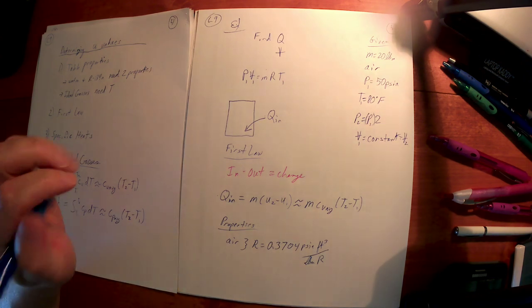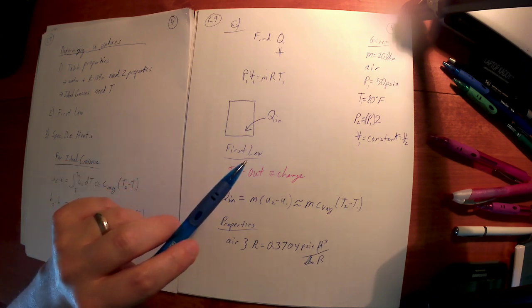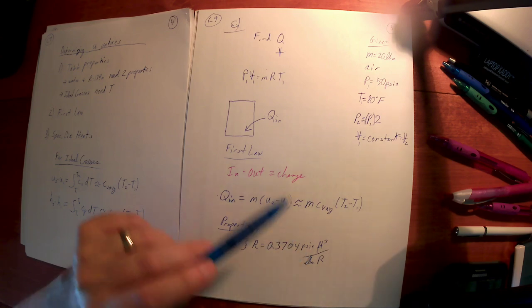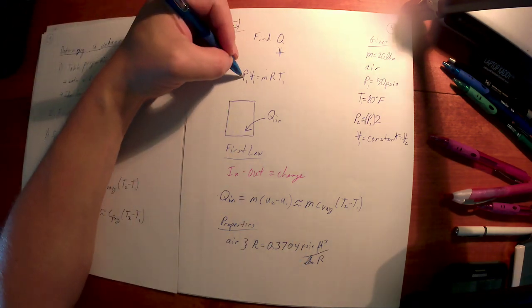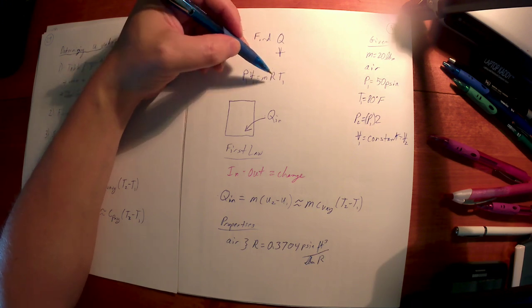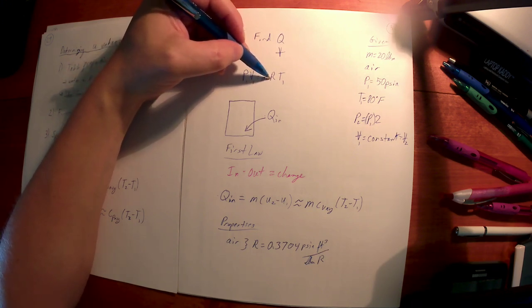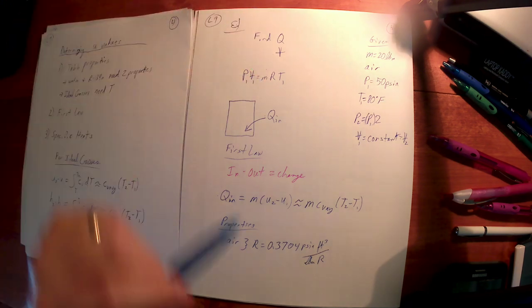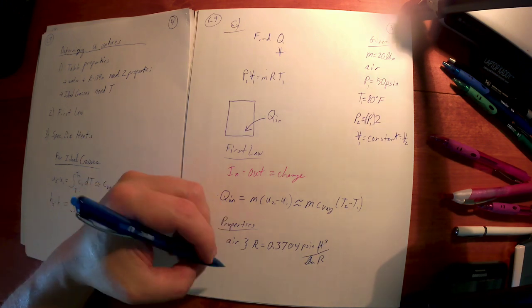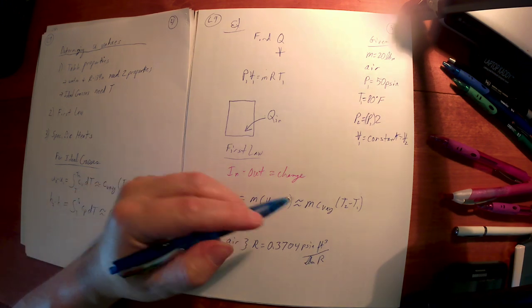All right. So now, Steve, why did you get this one and not the BTUs per pound mass Rankine? We'll look at the units here. This is going to be PSI. This is going to be cubic feet. This is going to be in Rankines. So I need something here that's in PSIA cubic feet Rankines. Again, you could use the BTUs per pound mass Rankine. You're just going to have to do some conversions to use it. All right, what about C sub V?